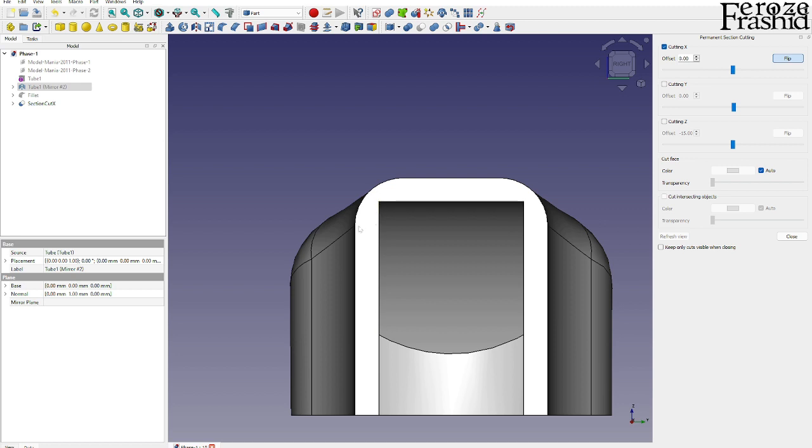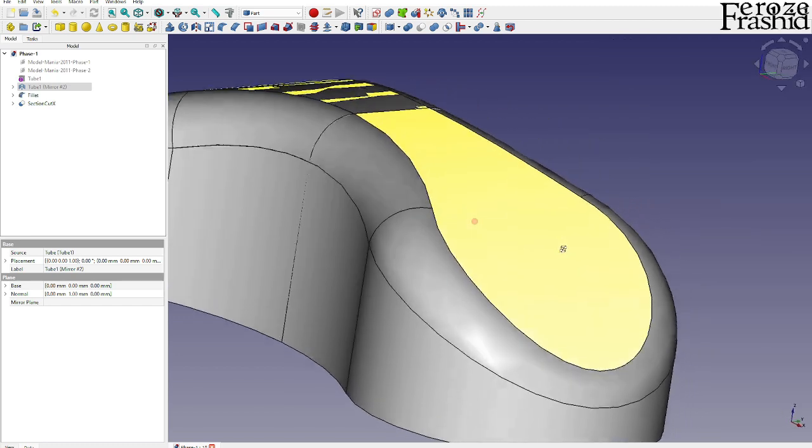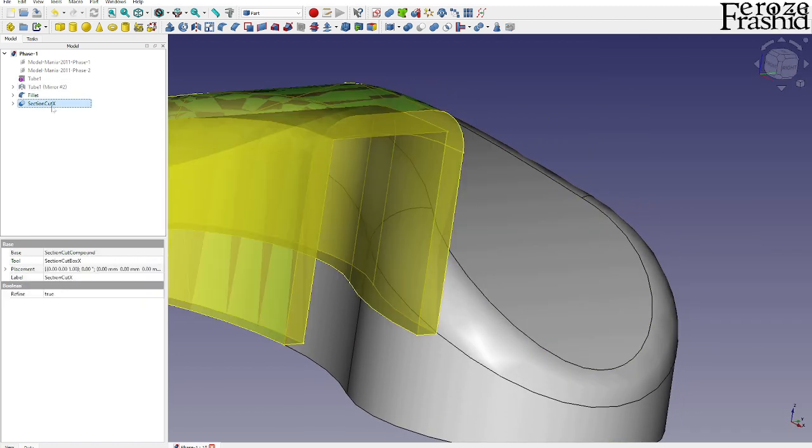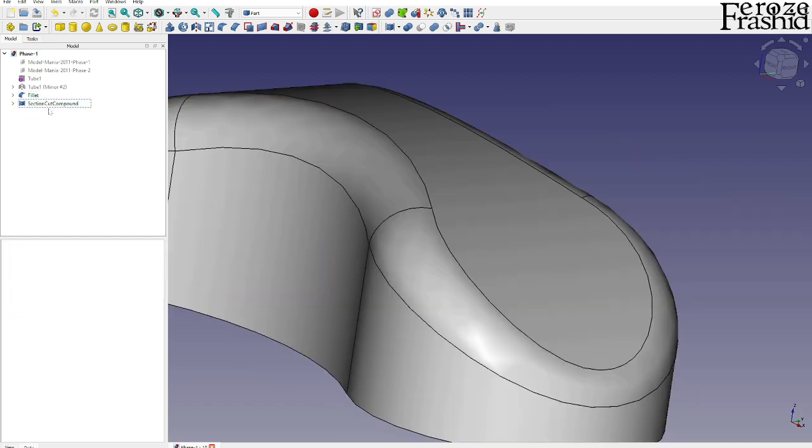So the thickness is 3mm here, but here it's definitely less than 3mm, so we need to bring another curve here. If outside is 6mm, we want to make it a 3mm thick wall, so inside would be a 3mm fillet. We close that part, we create something else. I'm going to go ahead and delete that.